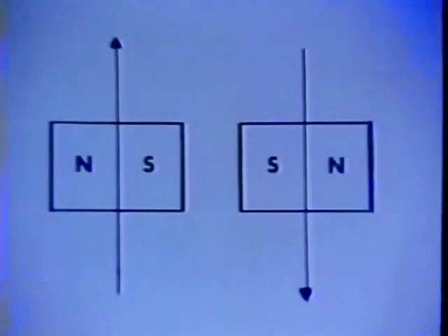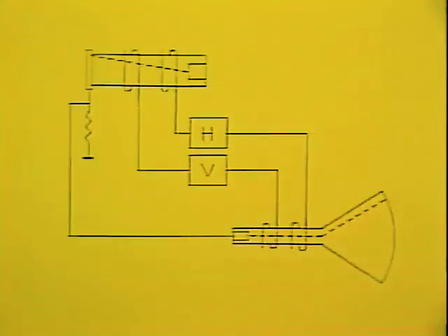The vertical movement is produced in exactly the same way. Another set of coils is used, and these are fed a signal from the vertical oscillator. This produces slow downward movement followed by a fast vertical retrace. We said earlier that the beam is blanked during the horizontal and vertical retrace periods. Blanking the beam is very easily accomplished.